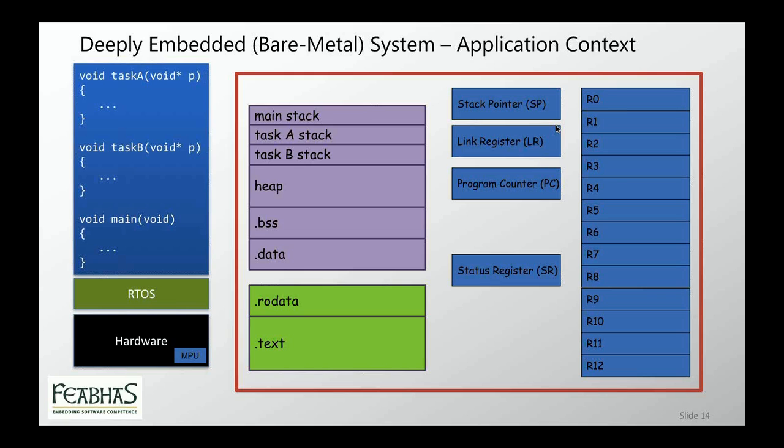So the MPU can be used, but of course we're still dealing with a direct linear model there. We're dealing with a flat address space, a physical address space. And the Cortex-M has a first degree of privilege level as well, so you have a privileged mode and user mode that you can swap between. It starts to give us our initial foundation of safety and security at the application level. If task A is running, then we can ensure that certain faults cannot happen, or if they happen, for example, an ill-defined pointer, that can be caught through the MPU, and an MPU trap into the processor exception model that we can then deal with in the appropriate way.